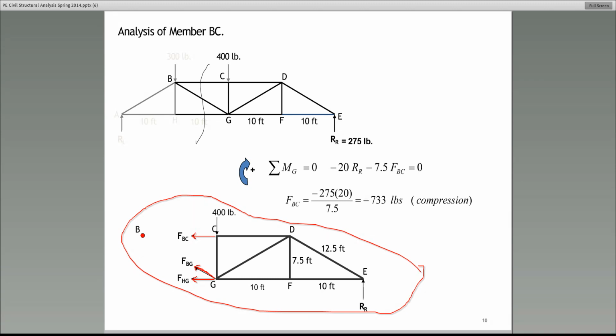Now, what about the external forces? Here, and this is very important, especially for those of you who have not done many of these kinds of problems since you left college. What about the external loads? Well, the 400 pounds, for example, is acting at the point C. So here's what you need to do. Is the point C part of this free body diagram? The answer is yes, it is. Then you will include that force.